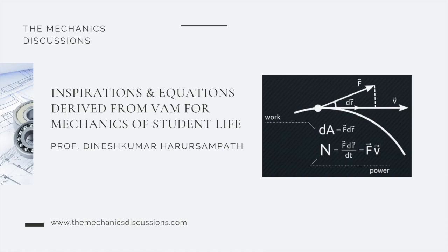Now, the whole idea of the variational asymptotic method, or for that matter any variational principle, is to have a functional and then try to minimize that and get the data from that. And in many cases, the variational principle can be used to do an analysis of the system without even deriving the governing equations and solving them.